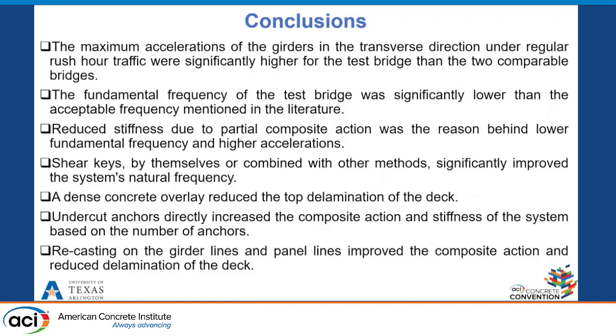Shear keys by themselves or combined with other methods significantly improved the system's natural frequencies. A dense concrete overlay reduced the top delamination of the deck. Undercut anchors directly increased the composite action and stiffness of the system based on the number of anchors. And recasting of the girder lines and panel lines improved the composite action and reduced the delamination on the deck.